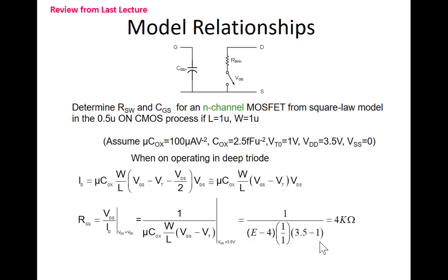Is that interesting? Because we saw that the switch level models determine the speed of the device. So this suggests that as we change the dimensions, we can change the resistances and the capacitances and hence change the speed. Maybe make it faster, maybe make it slower. But we have control of it. Make sense? Okay, so is our switch level model cast in concrete? The answer is no. It depends on the process, and it depends on the dimensions of the transistor you use.